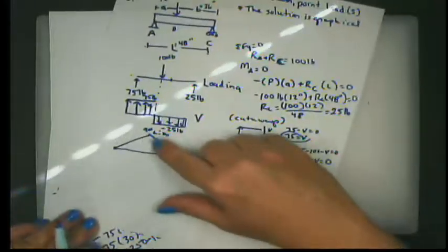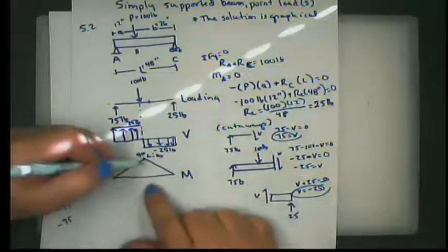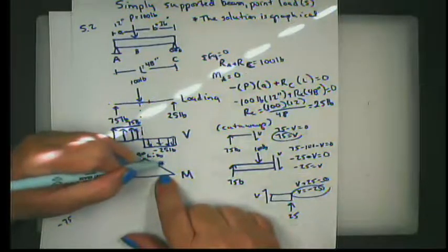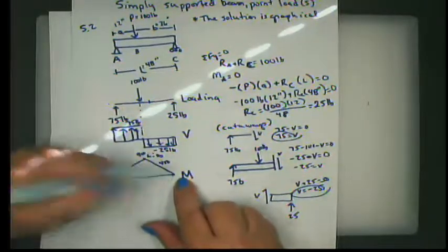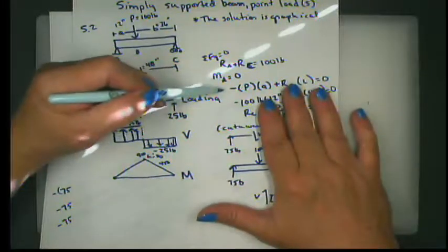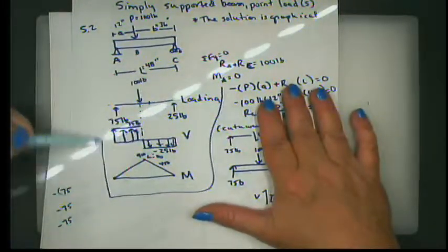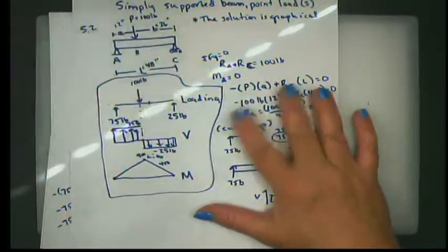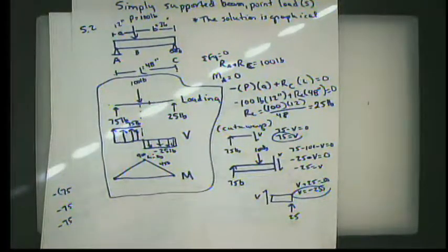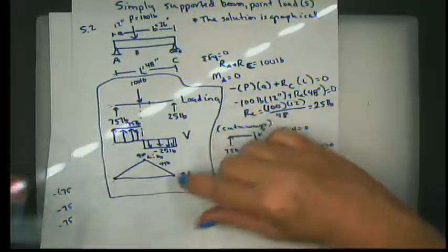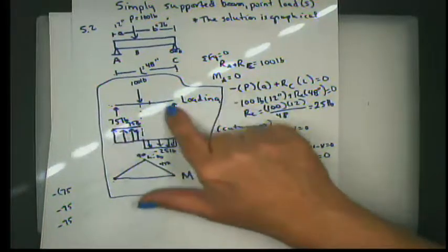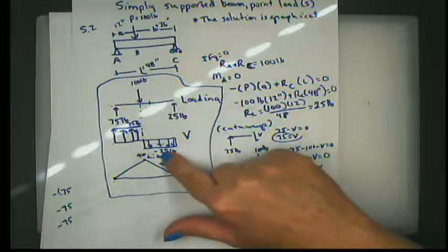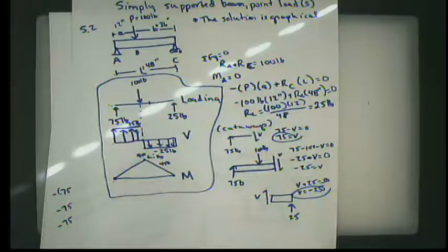So does that go along with this linear distribution? It sure does, doesn't it? So it's 900 here, halfway in the middle, the value is 450, still in inch-pounds, and here it's 0. So this is the solution to the problem. So in other words, it's not x equals this, or it's not an equation. It's 3 graphs stacked one on top of each other, each of the same length, each representing the length of the beam, showing the loads, the shear, and the moment responses.